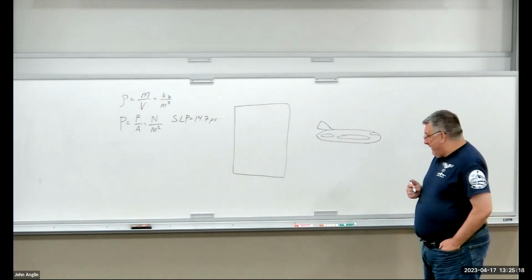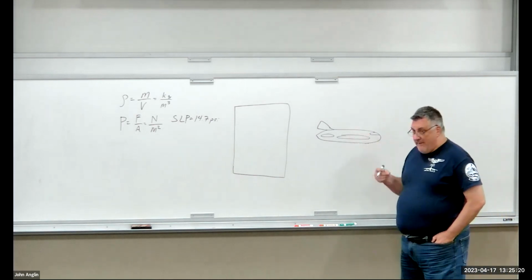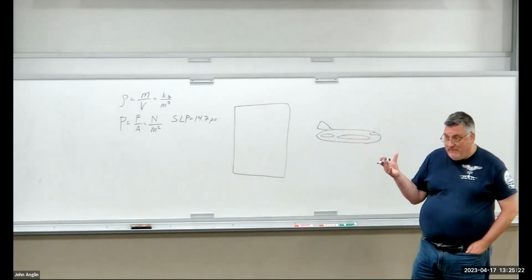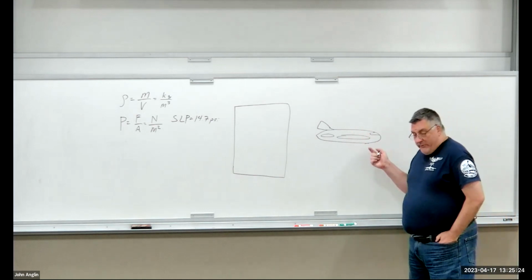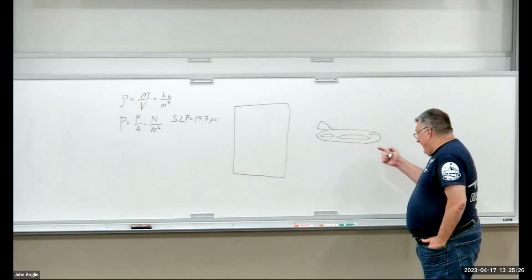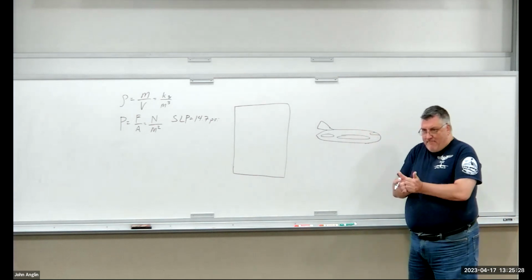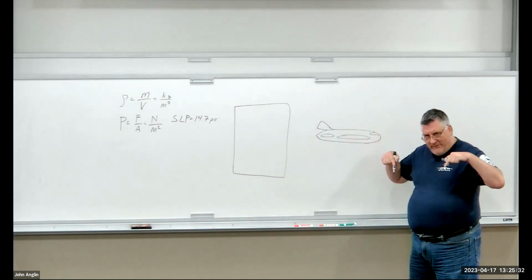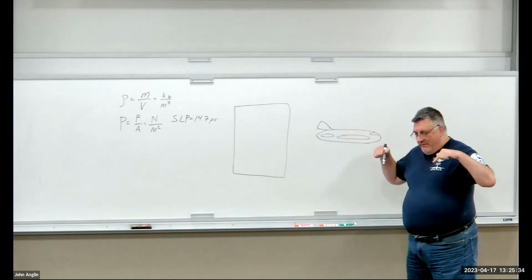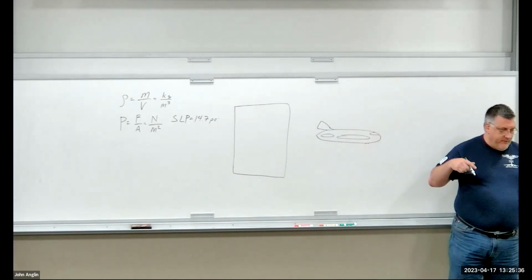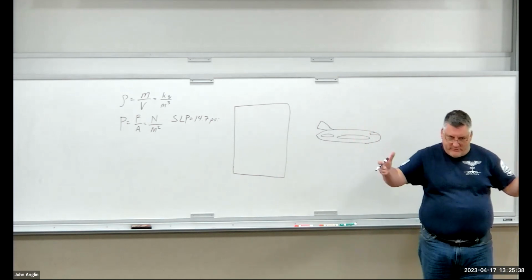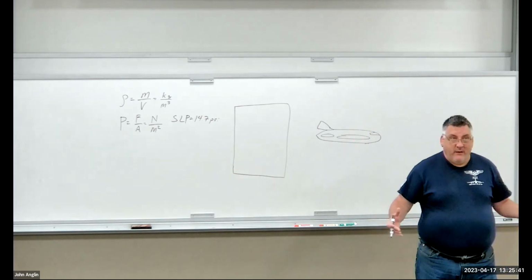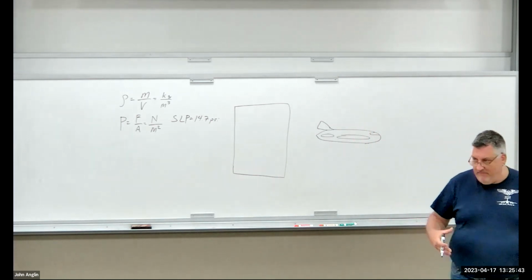Our differential pressure inside the aircraft might be 5 psi. And because it wants to be in equilibrium, it's 5 psi inside the aircraft pushing everything out. On the ground, you don't have the pressurization system on, so the pressure inside and outside the aircraft are equal, thus your PSID is 0.